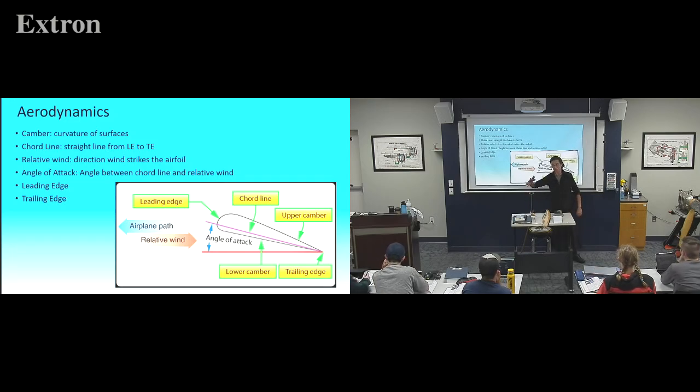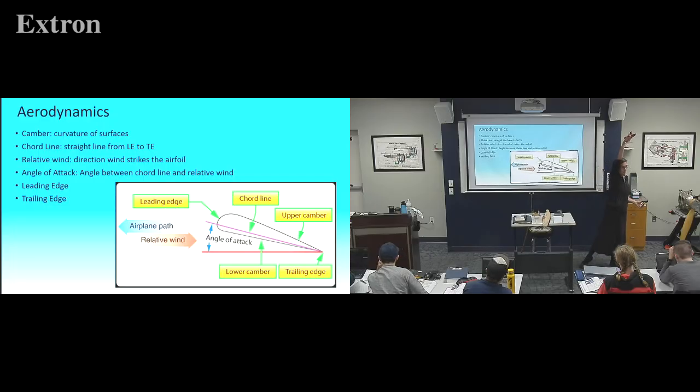It's actually due to the relative wind. I'm going like this, so my relative wind, or the wind the aircraft feels, is going to be right on the leading edge like that. Because all my airspeed is this way, my wind, and I can feel it with my hand, is coming right down like that. So even though I'm nose up, as long as I'm accelerating, I have a low angle of attack.